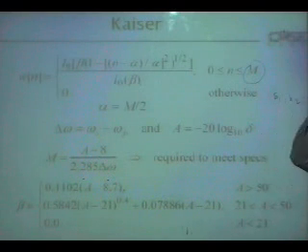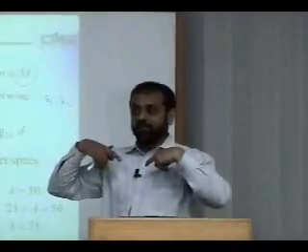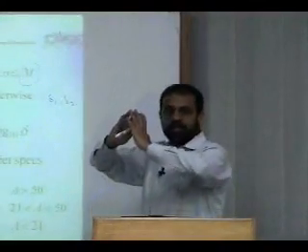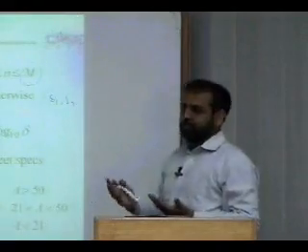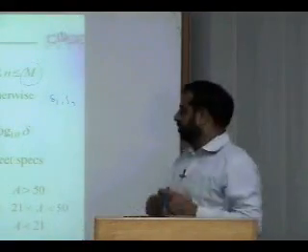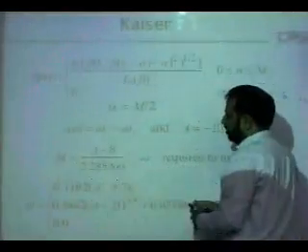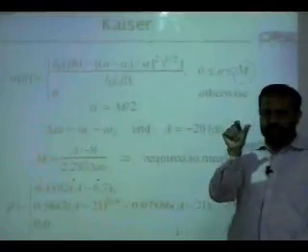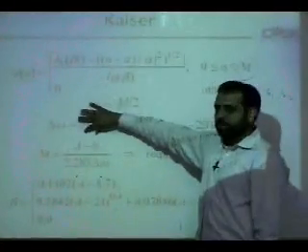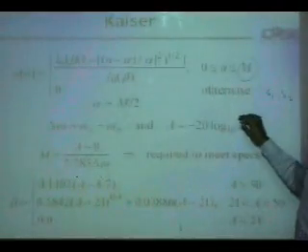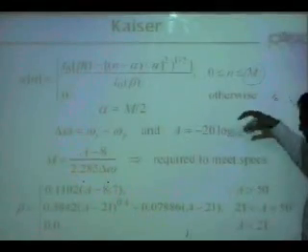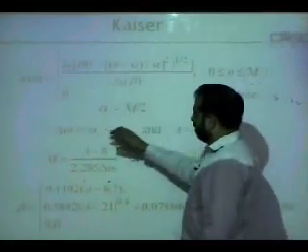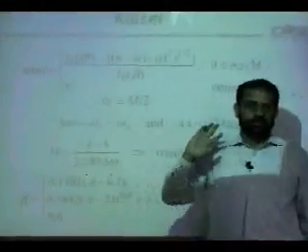You are basically keep shrinking the window in time domain, making it flatter and flatter in the frequency domain, and more rejection in the frequency domain. So m is computed from this formula. It's very simple to compute. As you can see from here, delta omega is the transition band. So it looks into the transition band, it looks into the rejection you want. So the rejection you want and the transition band will define the length of your filter for the Kaiser window.